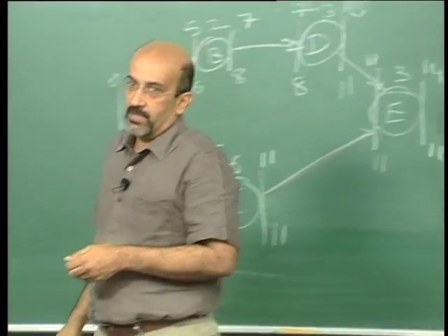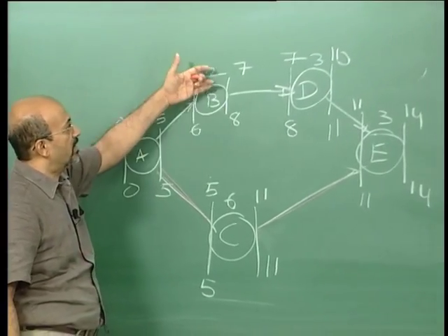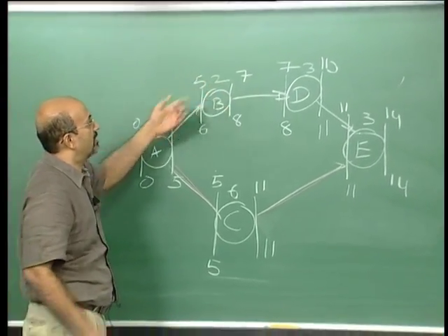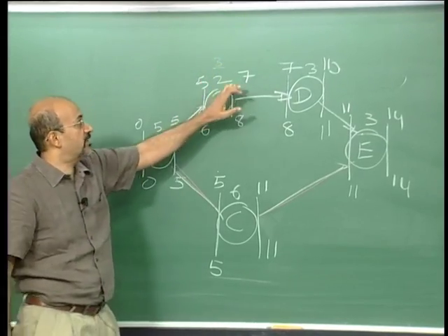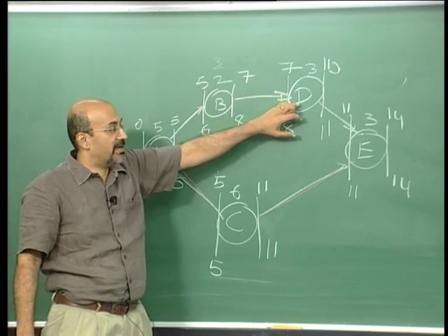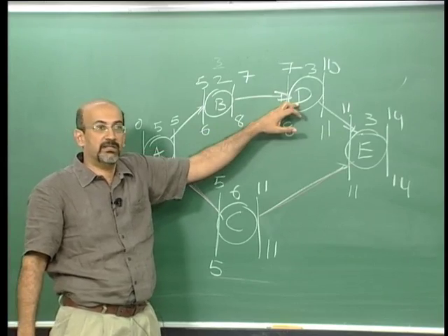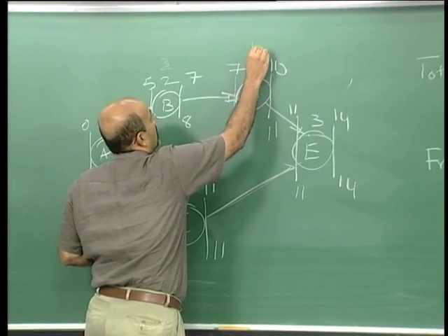So there used to be a time when CPM was new, B would look at his float and say, oh, I can take 3 days. It's okay if I finish on day 8. D will take a look at his basic information and say, oh, I've also got 1 day of float, maybe I should take 4 days.